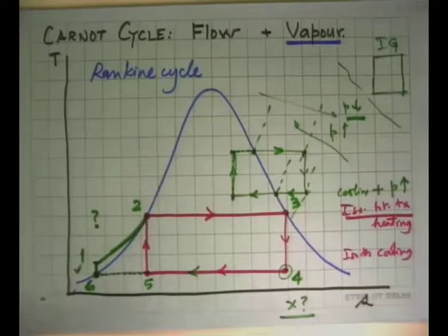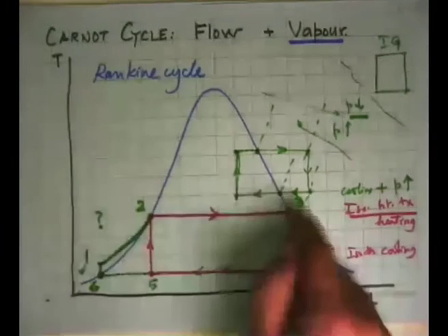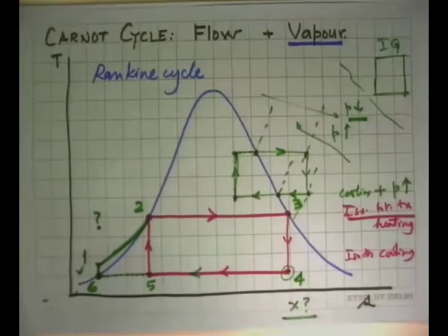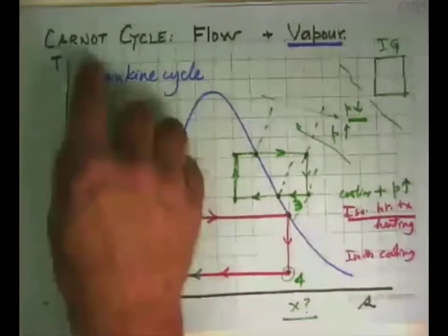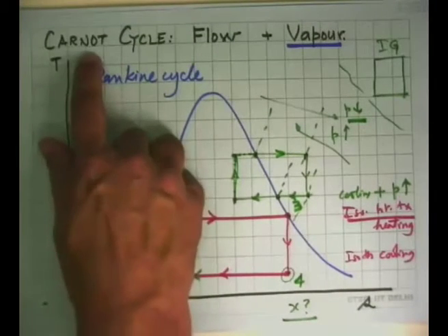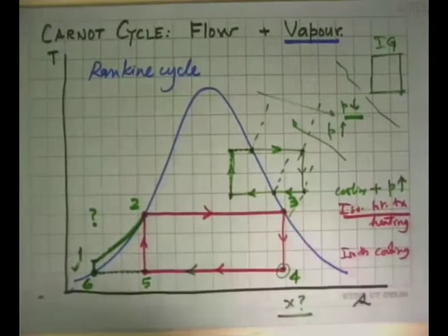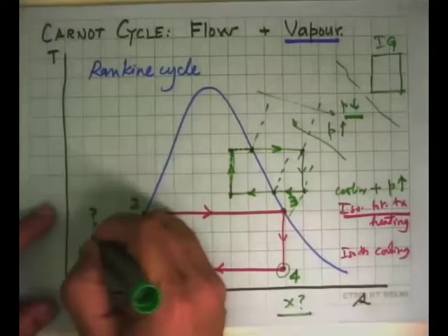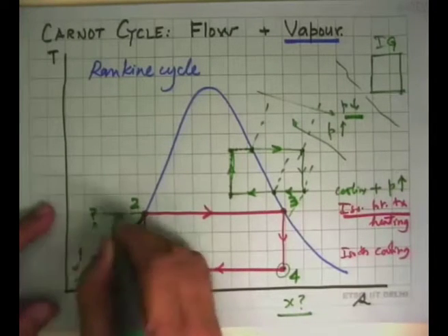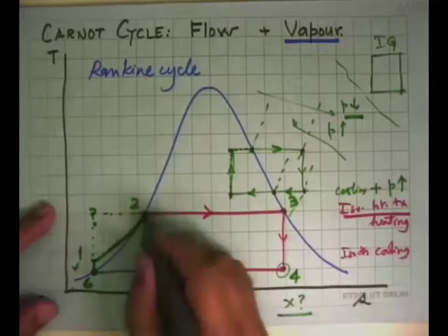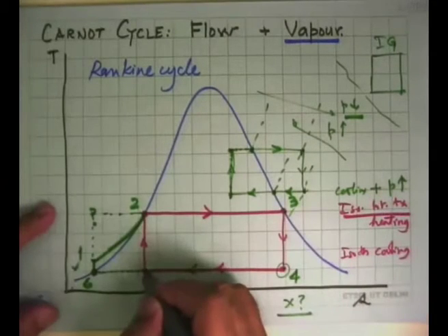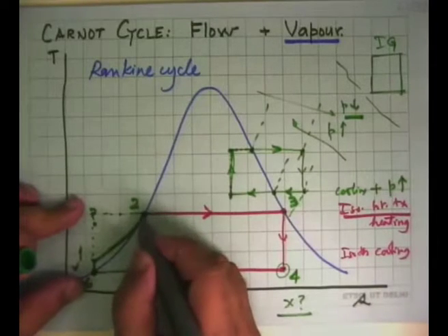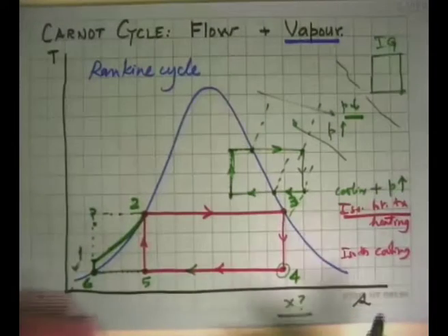So before we go there, let's look at this process 1, 2, 3 and see what it tells us about the thermodynamics of it, in the context of a qualitative way of looking at how good is my Rankine cycle compared to the Carnot cycle. Okay, the Carnot cycle, ideally, if we had made it up to this point, we would say, well, make a cycle which is like this. Then you would have got the Carnot efficiency, or this cycle would be the same Carnot efficiency, but what we have done now, instead of this cycle, which was the Carnot cycle, we have gone this. Our efficiency has come down, and let's see how and why and by how much.